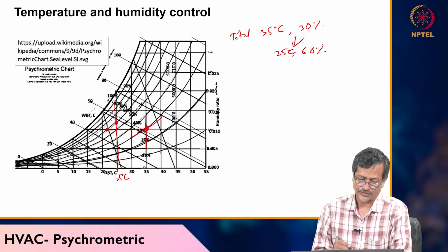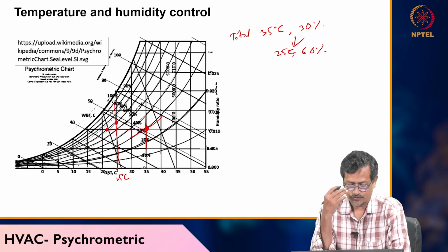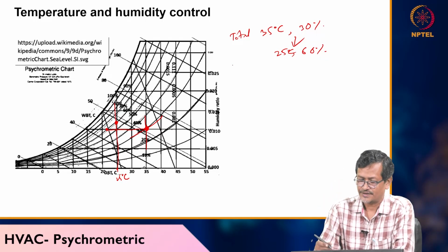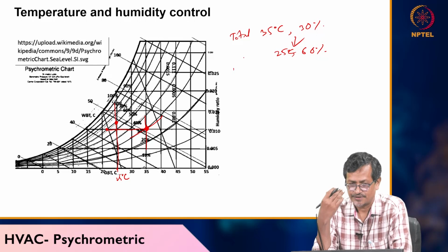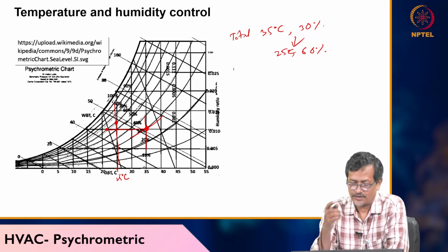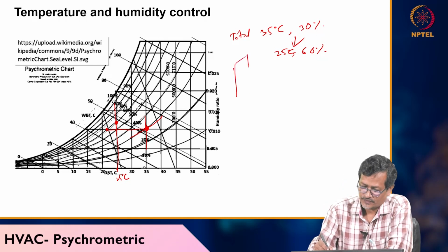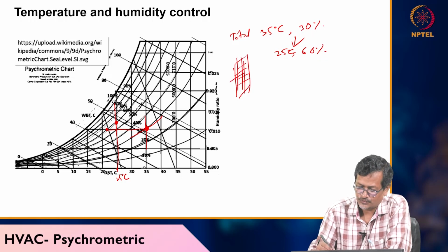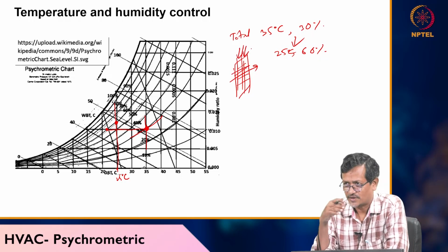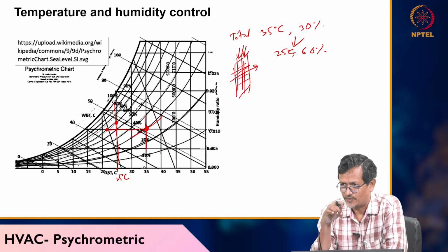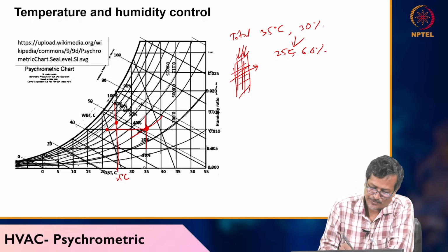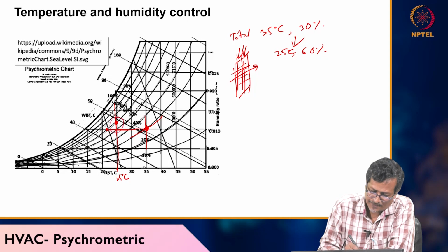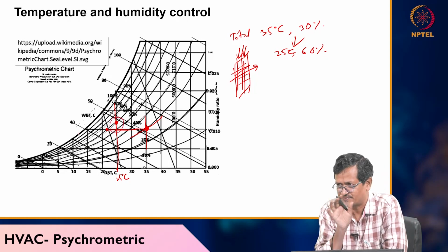So how can you do that? If you use a desert cooler, in North India you are using desert cooler, right? In desert cooler what happens, you have one cotton wick or some coir, through this air will be passing and you have lots of water splashes. That water splash will be adding lots of moisture. When we are adding moisture, actual temperature will be going down directly and it will be reaching your humidity nearby 60%, then you are feeling comfortable, that's fine.